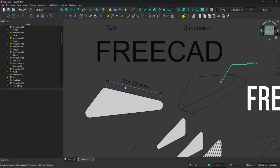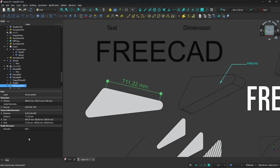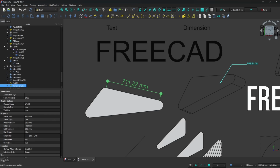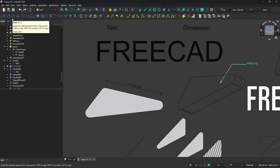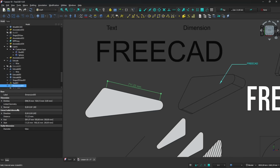Another important part we discovered is that down here we have the data panel, and this is also where we can sometimes change the parameters. Sometimes we can go also in the visualization or view panel right here. For example, with the scale multiplier, we can fix some problems concerning the resize or the scale. We find the scale tool here, but it doesn't work every time or for any object. So sometimes we need to do it another way, going into the parameters like the scale multiplier, or we can find a parameter right here.